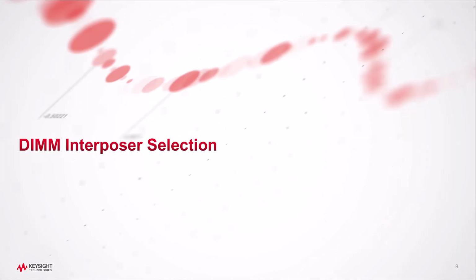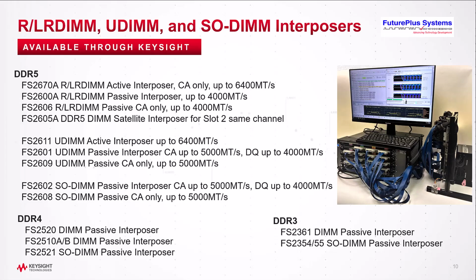Next, we'll go through the DIMM interposer selection. There are DDR5 RDIMM interposers available, UDIMM, and SODIMM interposers. Notice that for DDR5, because the speeds are going over 5 gigatransfers per second, for each of these there are options with the clock divider, so you can capture command address only at the higher data rates. And command address and chip select let you do complete protocol analysis and debug on the DDR5 bus. For the RDIMM interposer for DDR5, the FS2670 has not only the clock divider, but also a RCD.